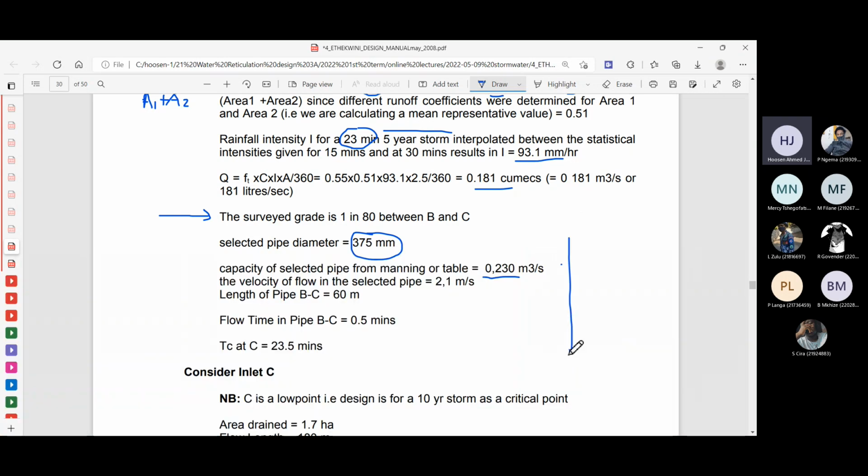But there's quite a bit of calculations missing from here. You'd have to go through what we've done in our sewer calculations and double check the actual velocity, check the depth of flow in those pipes and things like that, and just make sure everything works out well there.